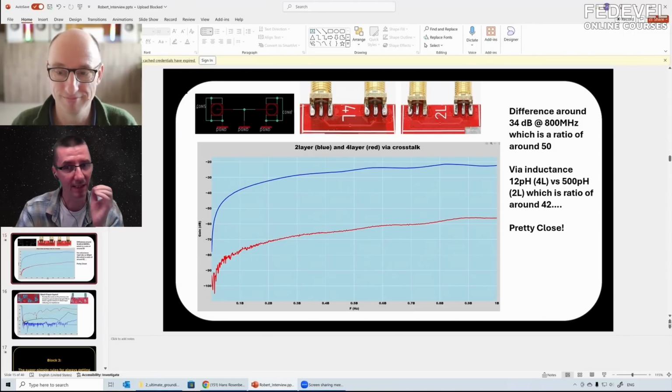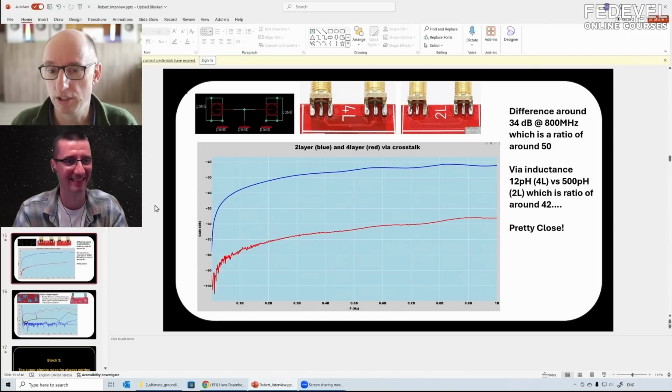Okay, and I think this is very important to understand, and it shows a lot of things for power delivery, because a lot of power goes through vias, and this can actually play a big role in power delivery. Yeah, if you're making something like an FPGA board, for instance, and you use a single via to get the power in, and the thing with these FPGAs is they have a core voltage of 1 volt, but they might be burning 10 watts.